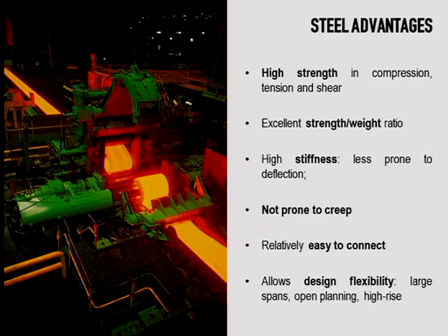That's important because you don't have to consider that during design, but it can still expand due to thermal expansion. So if you heat it up, then it would tend to expand. So you will still need to consider control joints. It's kind of easy to connect: rivets, bolts, it can be welded. So there are different possibilities to connect pieces together.